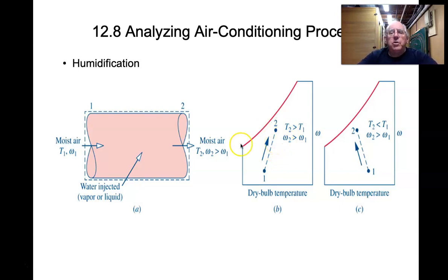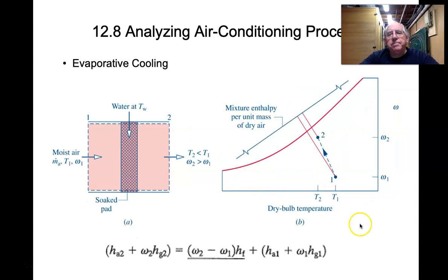This process here obviously would allow moisture to come in, but at the same time it also increases the temperature. So this would possibly be a process where you want to take cold or cooler dry air in the winter time and bring it up both in temperature and to a humidity value that is more comfortable. So that's the humidification process.